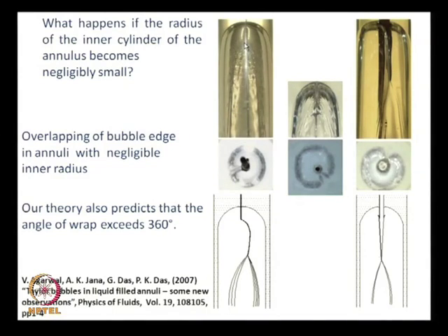What happened in this particular case? Actually, there was a cleavage at the tip. From the cleavage a line emerged, and then after some time the line bifurcated and water started flowing as streamlines in this bifurcated portion. It was a completely different shape as compared to the shape which we had observed for circular cases as well as the normal concentric annulus.